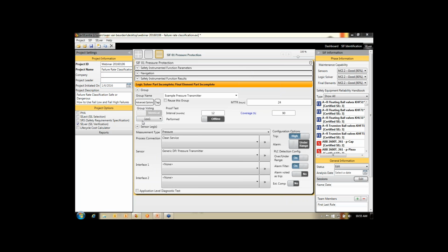You do it on the application level where you say, hey, I've got two measurements, let's compare the values. And you would expect that if there's a frozen output in one, and the other is still moving, that there's a deviation between the two results, and then you issue a deviation alarm, and you go out and fix it, or you transition to the safe state.